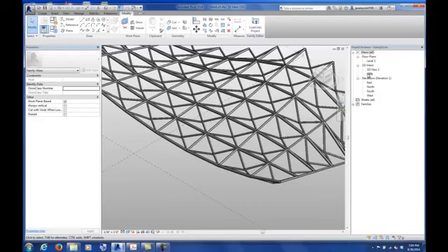Yep. So I've done everything, but every time I try and write the formula and apply it, it gives me this message. Change your radius, hit cancel on that. Your radius, click on that, hit modify under parameters, and make sure that that is an instance parameter. Yep. Instance parameters can only relate to instance parameters. So since the reporting parameter is an instance, the radius parameter has to also be an instance as well.